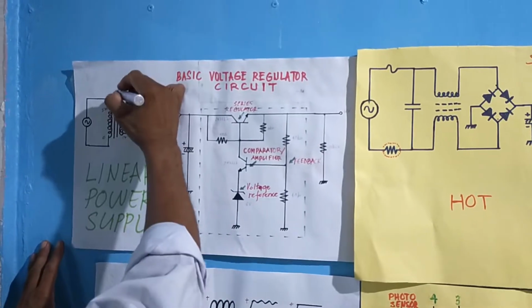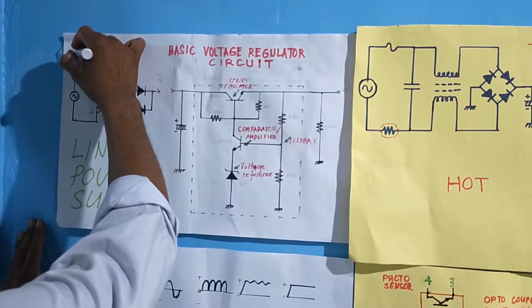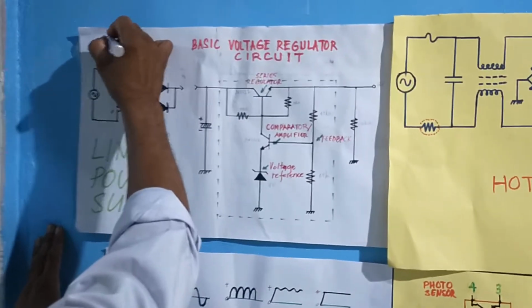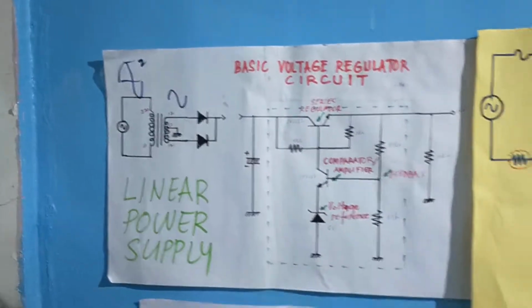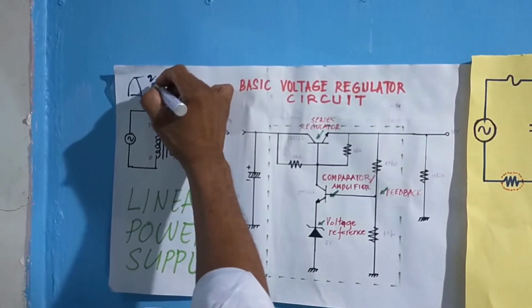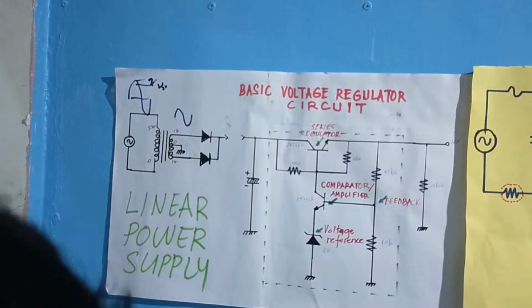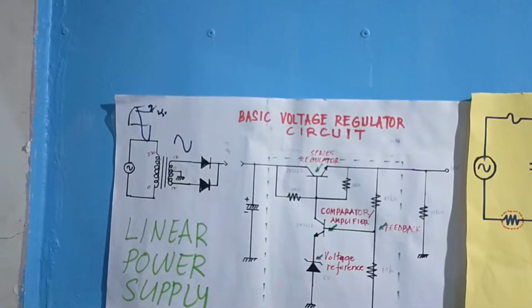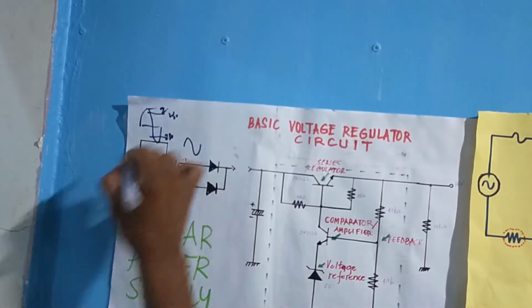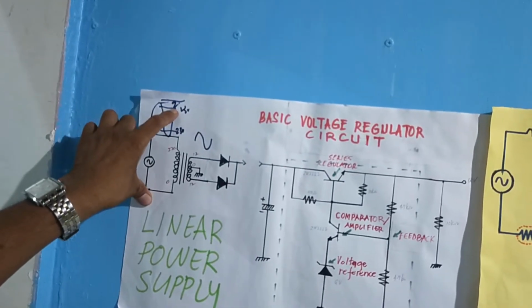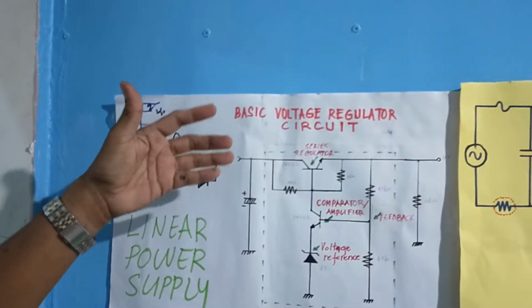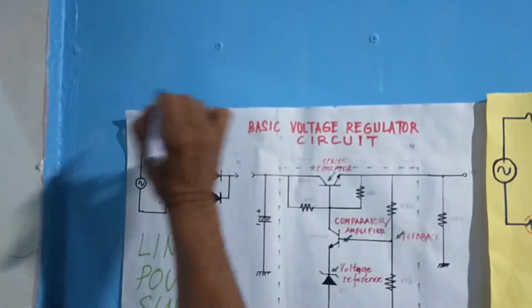This rectifier diodes now will rectify this voltage here, because the voltage at the primary is 230 volts RMS, the measured value here, it is still an RMS value. 230 also here. But the peak value, if you are going to multiply 230 volts with 1.414, will reach 300 volts above. 300 volts above. No?